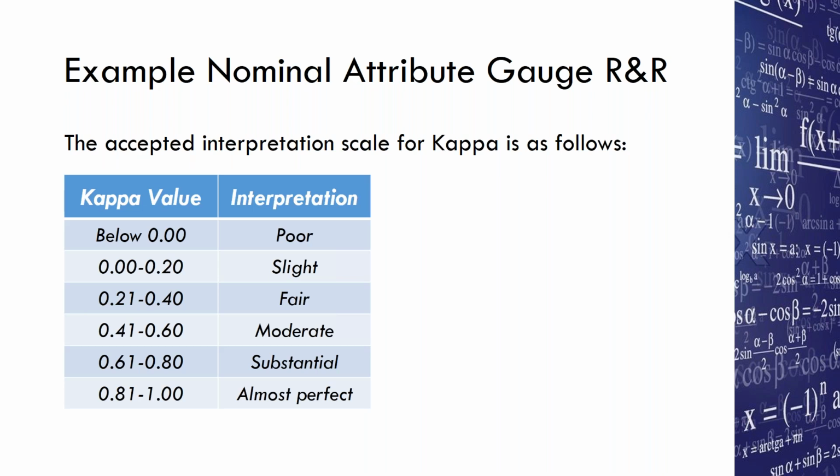When we did the attribute agreement analysis on it, we got a fairly good result, but the kappa value only came back at about 0.85. And I was one of the assessors, and even in that case, I had some cases where the first time I assessed it, it was upside down. And then the next time I assessed it, the gauge said it was right side up. You can imagine that could have put us in quite the quandary at Ford Motor Company if we missed just a single one.